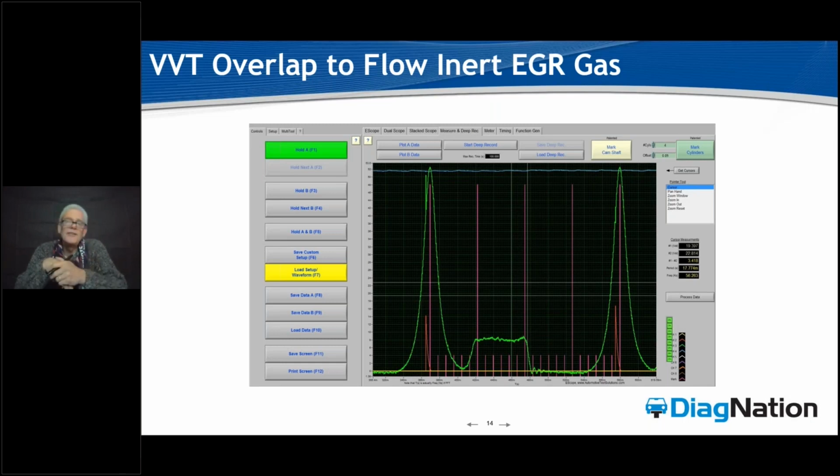And what I'm learning with these gas direct injected cars is if you consider the depositing coming from the intake side and following that valve, in all GDI applications, the swirl and tumble that's engineered into the way that air loads into that cylinder is now affected.